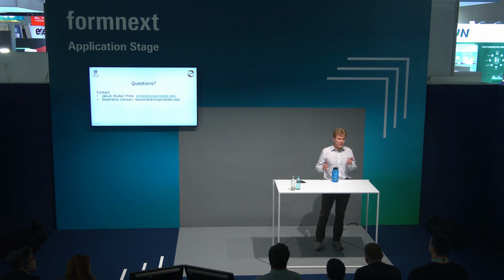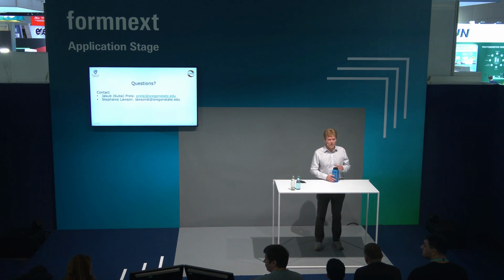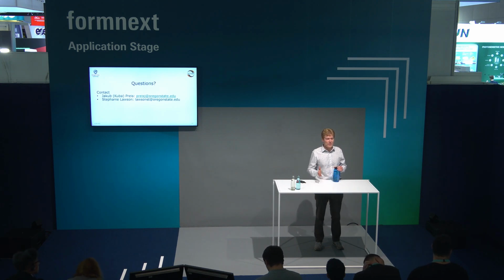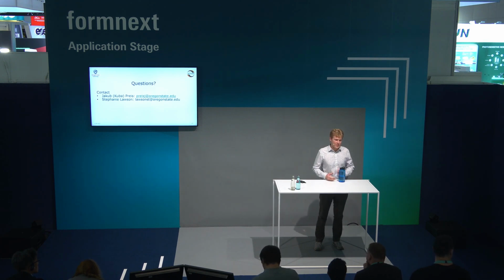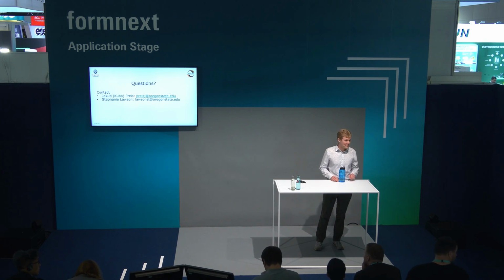I mean, if you have any sort of remelting, so if you use a liquid-based process, you're going to get some of the challenges that result, like solidification cracking and brittle phase formation. You can even sometimes get that if you use a solid-state process. What we have found is that a lot of times we'll have different sorts of failure mechanisms if you use LPBF versus LDED. That also has to do with the cooling rates of the two processes. Okay, thank you.